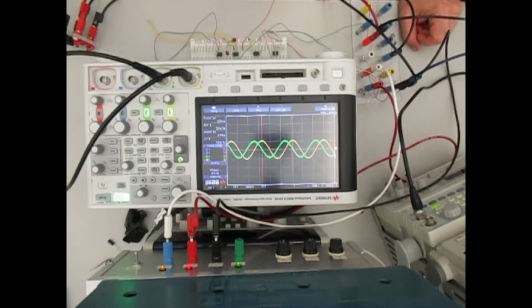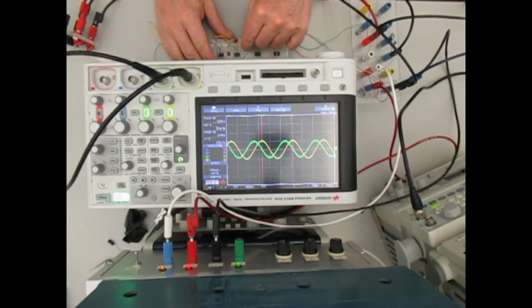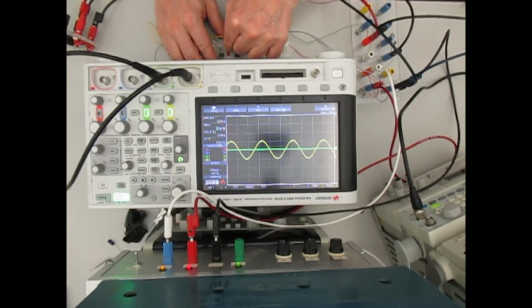So again, when we're using these circuits, you have to design them for a certain frequency, and these ones were designed to be operating at a very low frequency. Okay, so now we go to the integrator, and the integrator can be kind of tough because the capacitor in the feedback can sometimes charge up. So we'll see what we can do about capturing a waveform here.